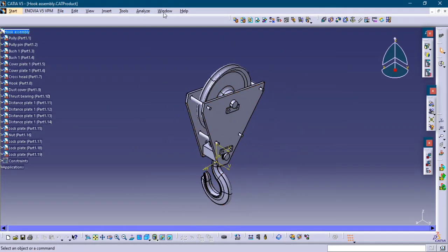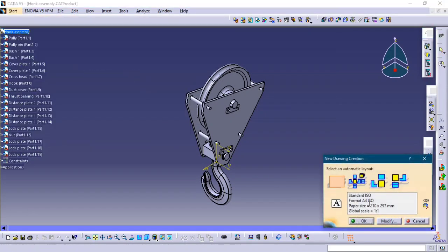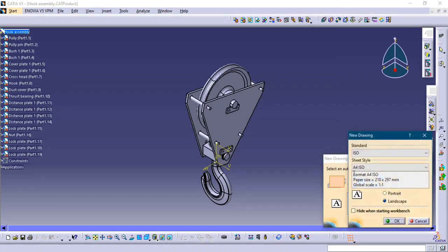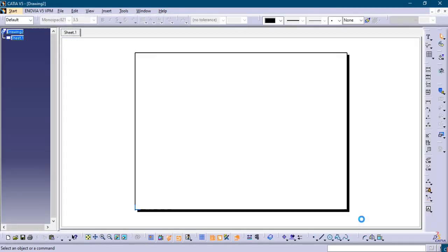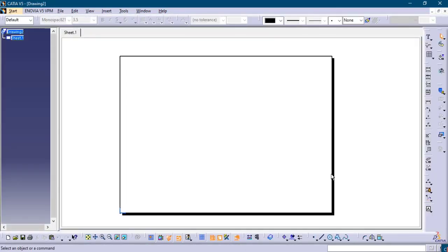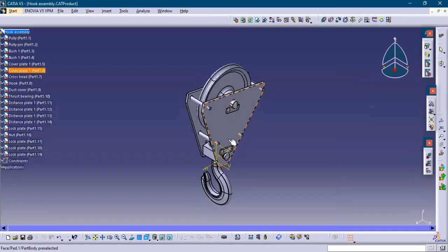Now click on the front view, or else you can use the isometric view, and window, and click on any of the orientations. That gives us the isometric view. It is somewhat bigger than our page, so I'm changing its size. Right click, properties, view scale. I'm decreasing it to 2. Click OK. Now the size is okay.